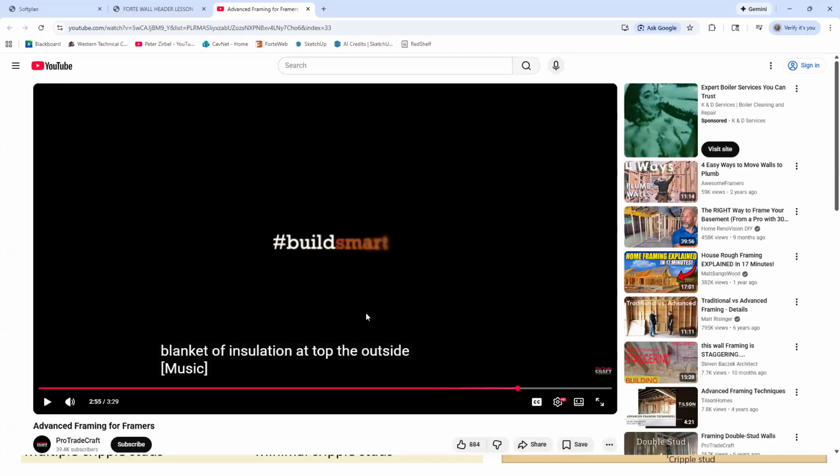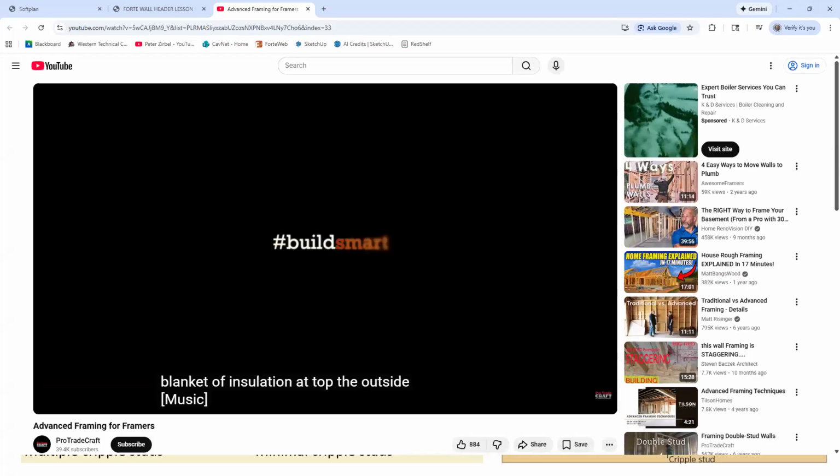So I know they said in this one, if you're totally concerned about energy, yeah, you can get rid of headers if they don't take a lot of load or any load, or you can make them very small if they take light loads. But that's not the way it works in the real world, in my experience. You just do the worst case, make sure the 2 2x12s work. If it doesn't work, like for a really long header for a garage door, then you do LVLs. Now, that's the way Habitat rolls. We have a new Habitat construction coordinator that comes in to talk to us next class, and we'll see. We're going to ask his opinion on how he wants us to build the house.